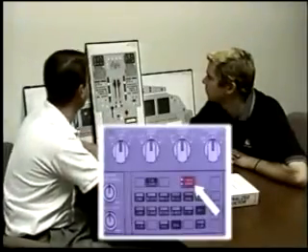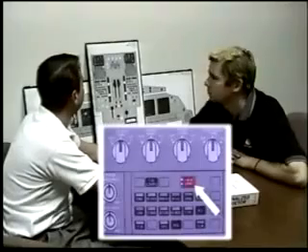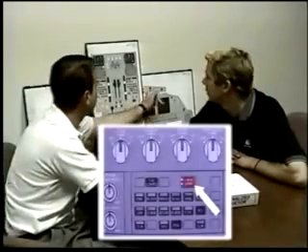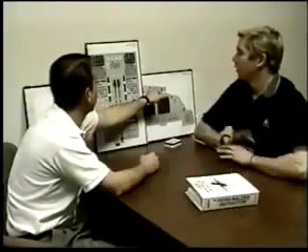Emergency cancel, and let me break this down into 2 parts. You get a level 3 repetitive chime and a master warning, but instead of selecting the master warning here to silence the aural, you select emergency cancel. What does the emergency cancel do in that scenario? It just silences the continuous repetitive chime. That's all. So what's the difference between selecting master warning here and emergency cancel?